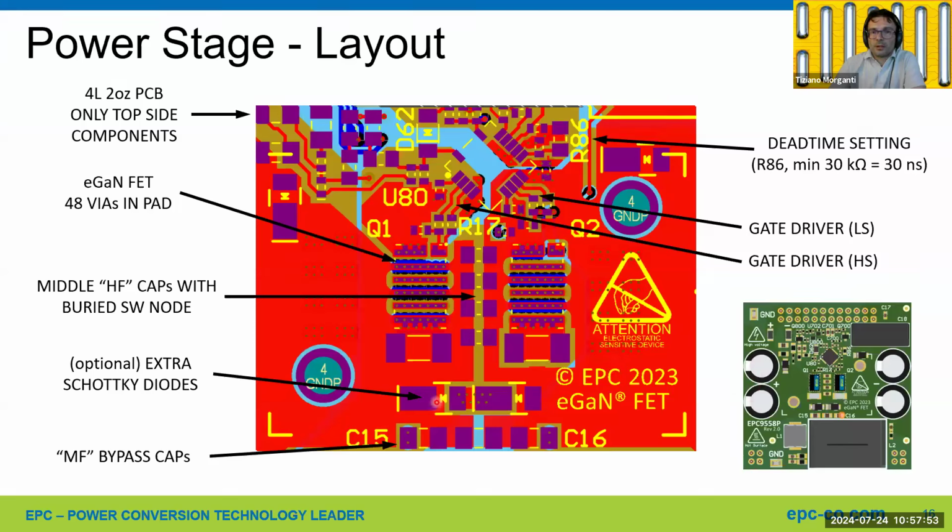So, having to redesign this, of course, we remove the diodes. I would just put more capacitors, so duplicate those 3 instead of the diodes. And I would also either increase the number of those capacitors, the electrolytic ones, or select carefully lower ESR ones, because the capacitor we use is about 100 milliohm ESR, might get maybe 50 milliohm at higher temperature. But still, it's a significant resistance that we want to get rid of to reduce the losses.